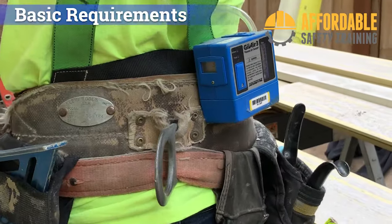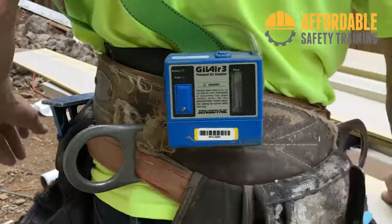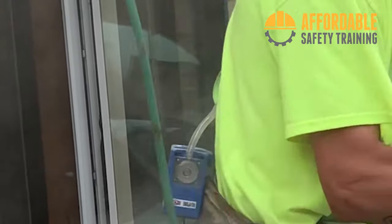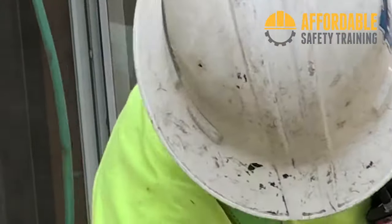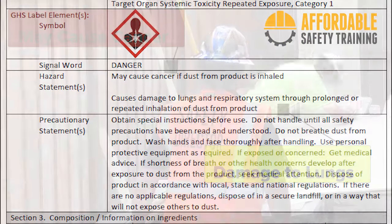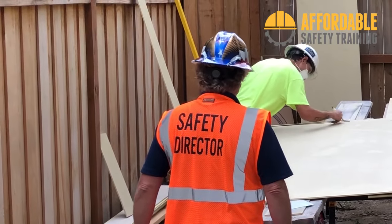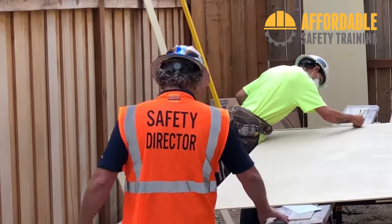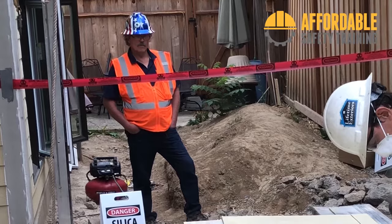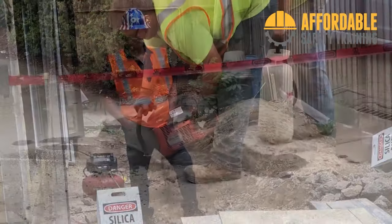The employer must survey the work area to identify respiratory hazards, and develop a reasonable estimate of potential employee exposure. The sampling must be representative of exposure levels, time, and working conditions. Check the safety data sheets for information on potential respiratory hazards. This analysis should be done by an appropriately trained person. If there is no one at the company who is trained on atmospheric analysis, the employer will need to bring in a professional. Free assistance may be available from your workman's compensation insurance carrier, or a local OSHA office.